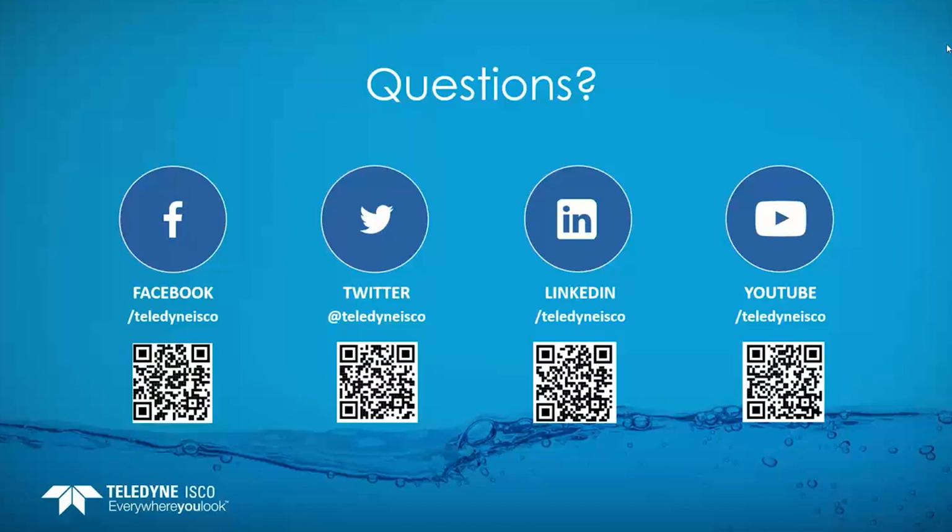Okay, perfect. We have another question. How do I accurately read flow during a submergence? Yeah, so the answer is it depends on your flume. For this example, we'll use a partial flume. In that case, if you are submerged, there's a ratio that you can look up in the Teledyne ISCO Open Channel Flow Measurement Handbook. It dictates all of those ratios.